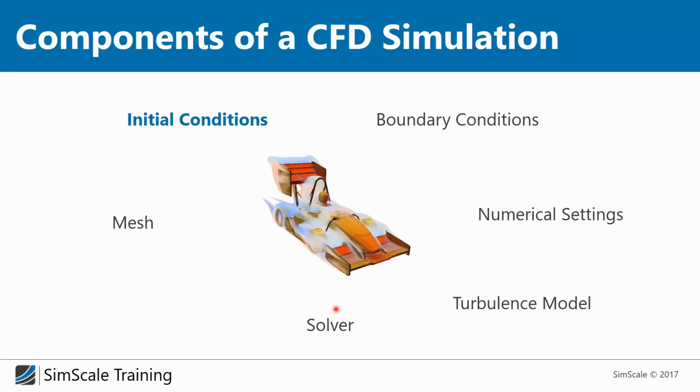To understand the initial conditions, you have to consider the fact that these equation systems are solved iteratively, which means we are calculating a first iteration that gives us a result which is far away from what we're looking for, and we're taking this result as a new start vector and repeating it again and again until we reach certain convergence criteria.